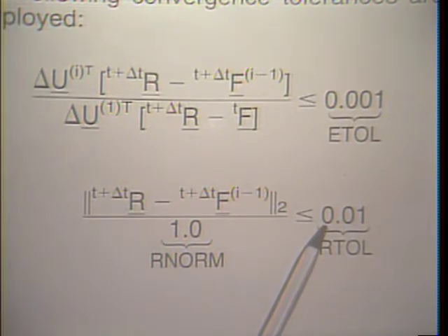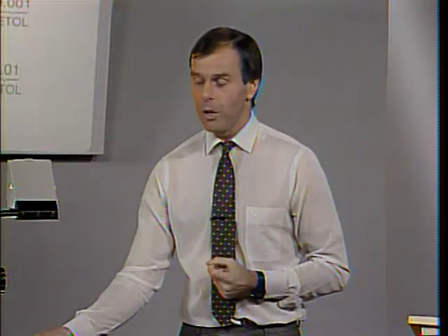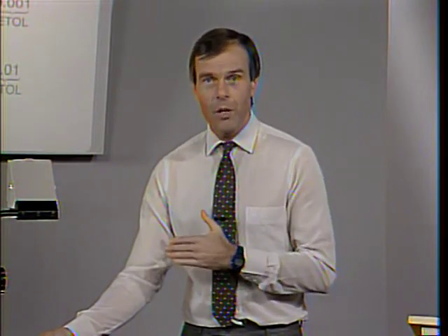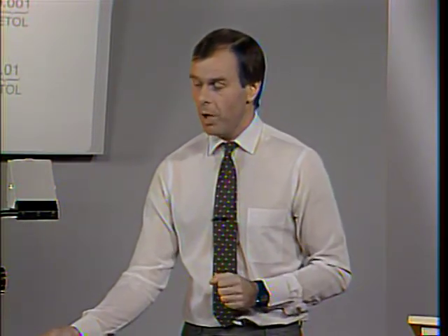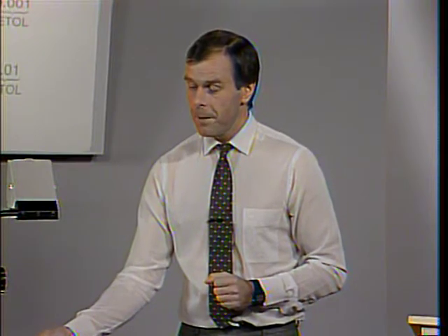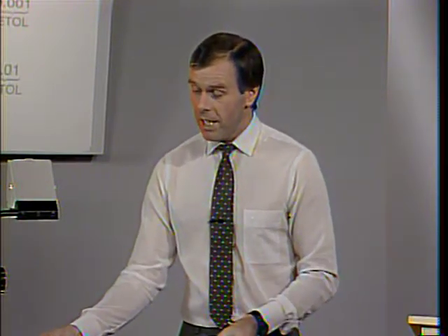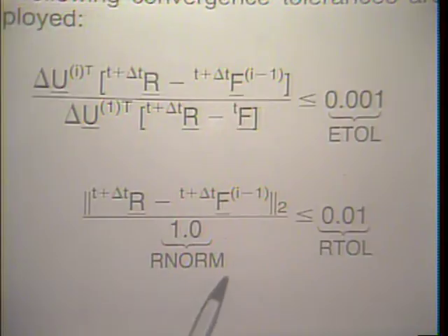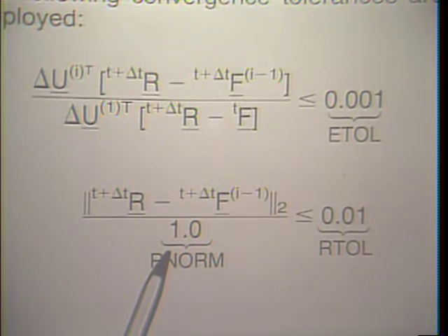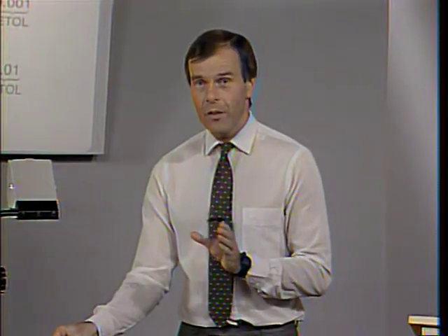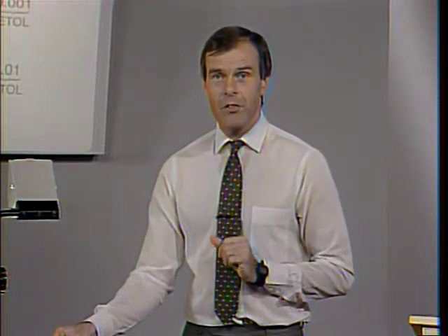In the computer program that we are using, the Adina program, of course, there are default values, which are really working quite well over a large range of nonlinear problems. And those, of course, are used very frequently. The R norm here you have to select, and this is a reasonable number when you compare it with the total load applied to the cylinder. Notice that we are looking here at 1 radian of the cylinder. It's an axisymmetric analysis.